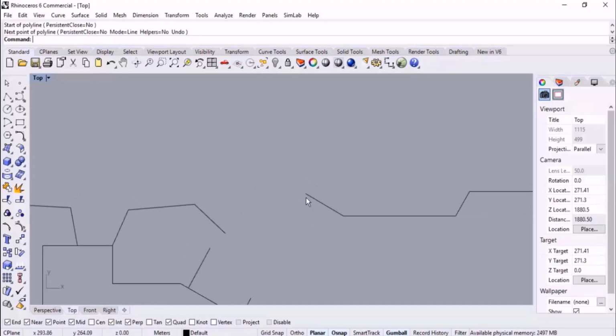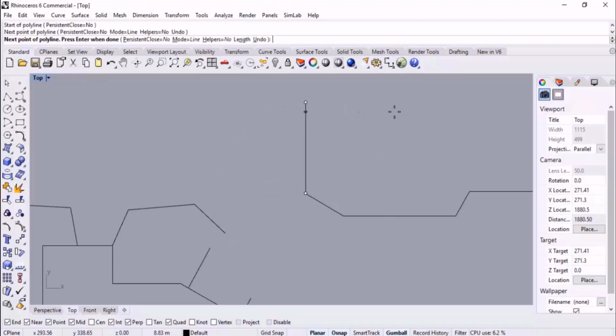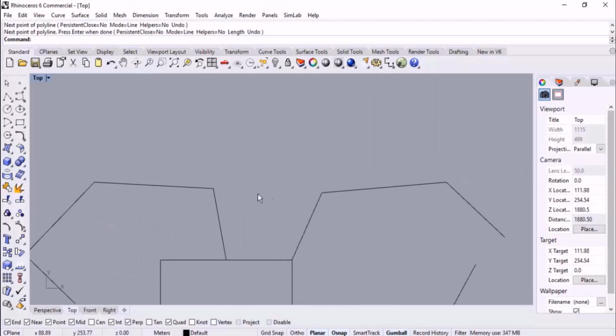Another example, for example, I want to sketch a line at this size or at this length, but in a different direction. I sketch it, but I do not click. I hold the marker, and then I press tab to restrict the direction and length. After that I can specify the direction this way. And I release shift to sketch the line. So this way we can measure a distance and then associate it to the line.